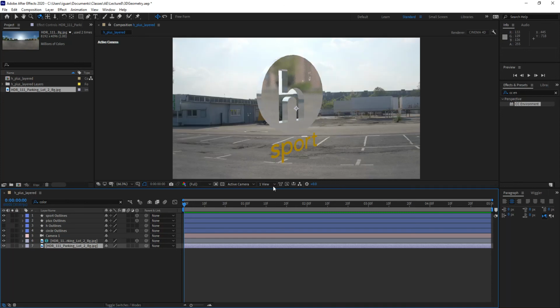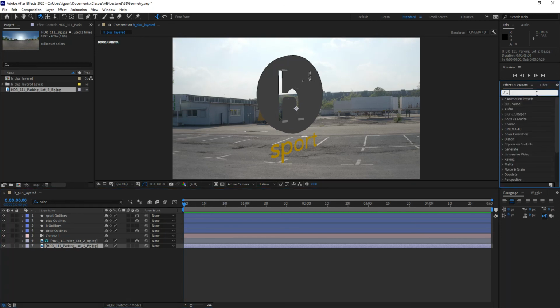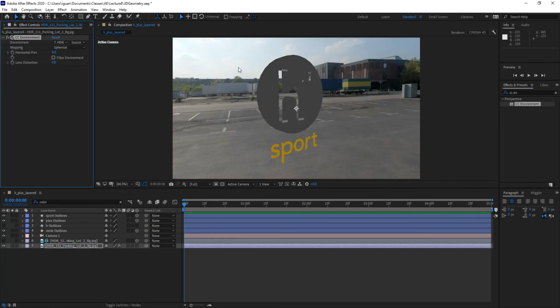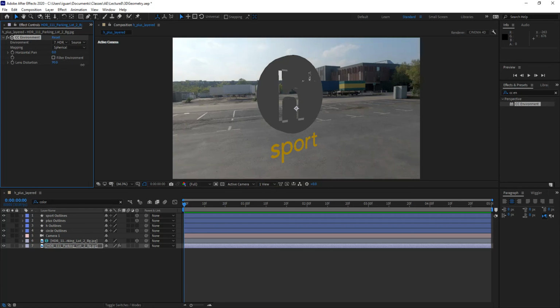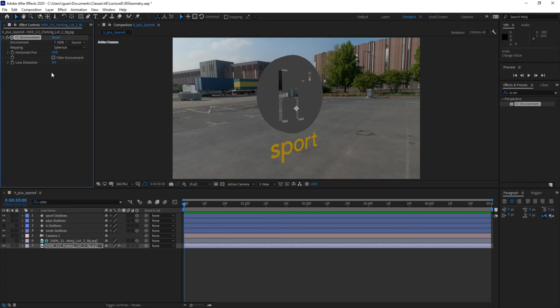You notice that it's going to look like a flat image again. Let me turn off the visibility of the reflection and the visibility of the environment. I am going to then, from my filters presets, look for a filter called CC Environment. That CC Environment option, I can apply to that HDRI image in the background, and it allows me to increase the lens distortion of an image to make it more distorted, or to pan, to rotate the image around if I need to.